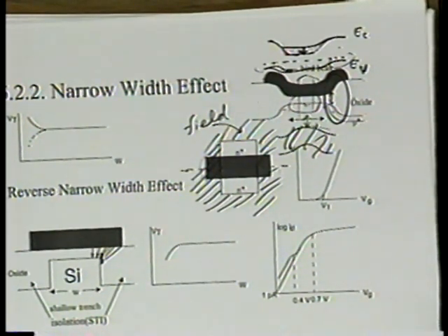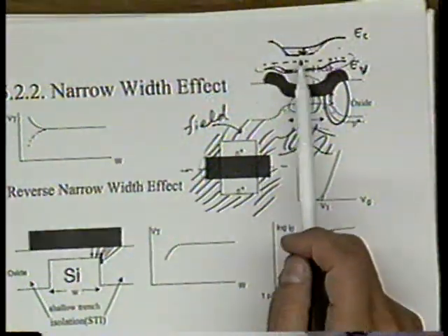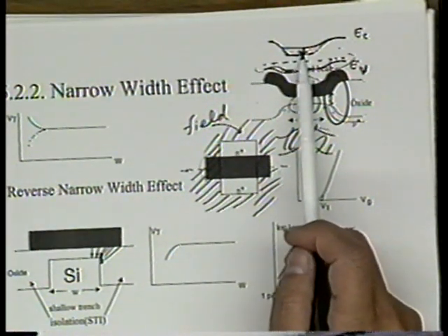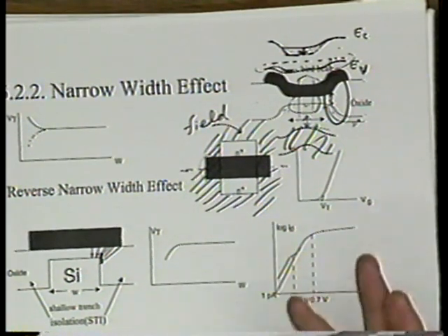Is that right? If you don't see it, make the W even smaller. Do you see now? The same VG should not be able to bend this down as much. If you still don't see it, why don't we make the W even smaller? This is the exercise I asked you to do last hour to think about the short channel effect, right? If you don't think the drain is going to lower the barrier, make the drain even closer to the source. Same thing here. Is that right?